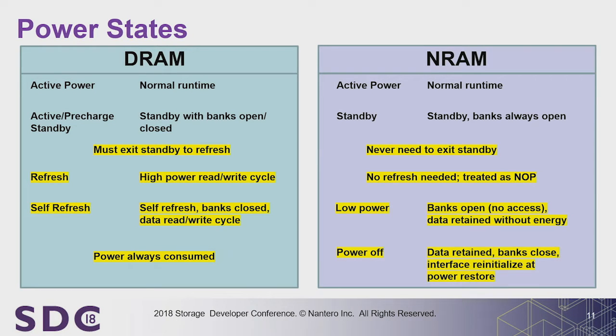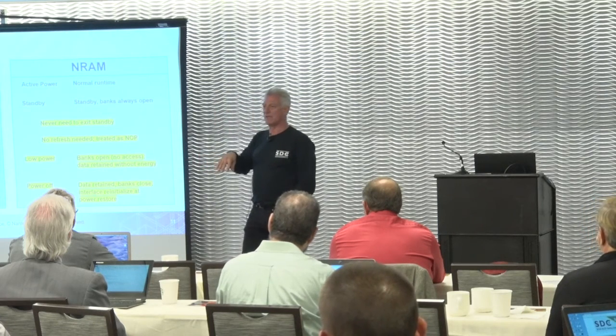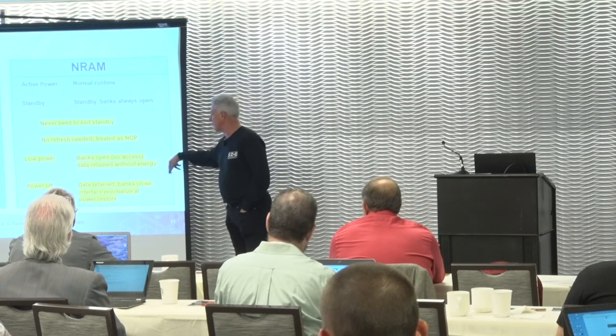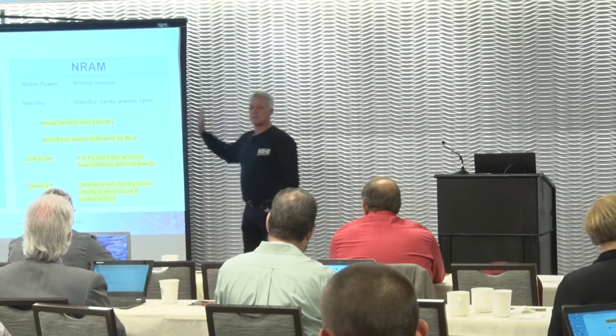Power is a great one. So with the NRAM, there's no self-refresh mode. You don't need self-refresh mode. The only time you do anything like that is if you want to change the operation frequency, you want to shut off the DLL and turn it back on at the new frequency. That's the only time we need anything resembling a self-refresh mode, because data is retained all the time, and you have no power burn if you're not using the device.